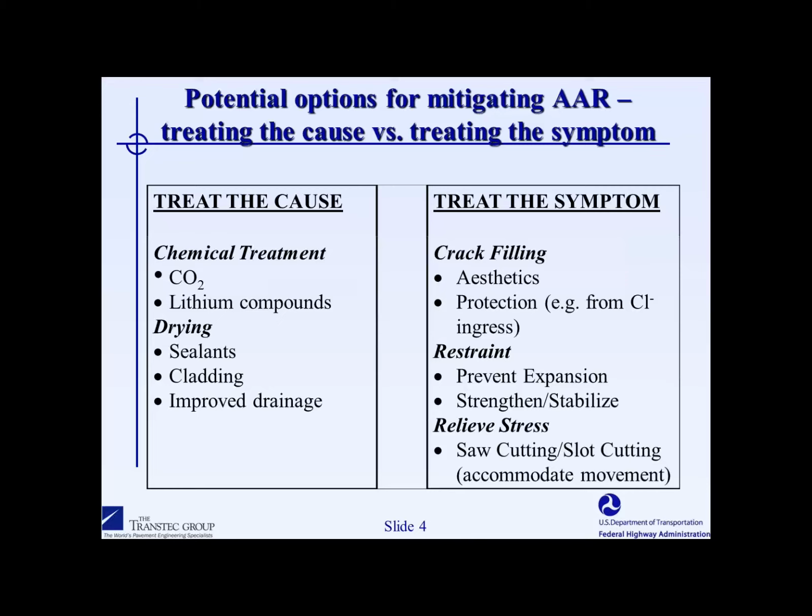Carbonating concrete that has reinforcement in it would lead to corrosion, of course, and also injecting ASR affected concrete with pressurized gas could lead to additional microcracking. So this isn't something that we recommend nor that we have tried in the field, but it has been mentioned as a potential way to deal with structures.